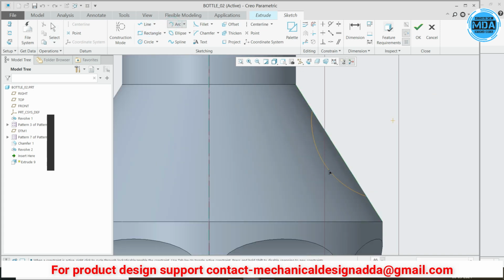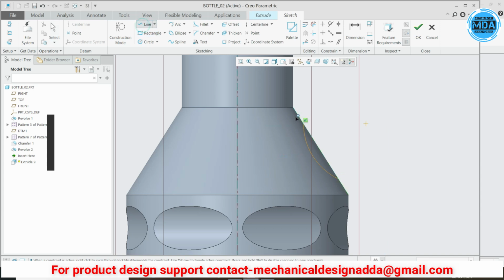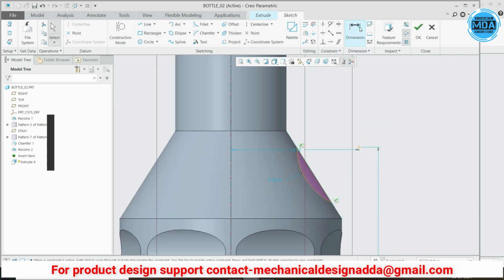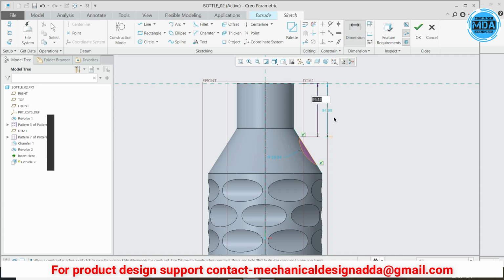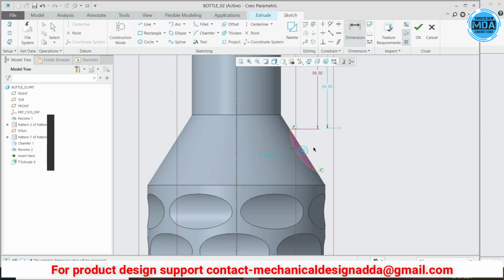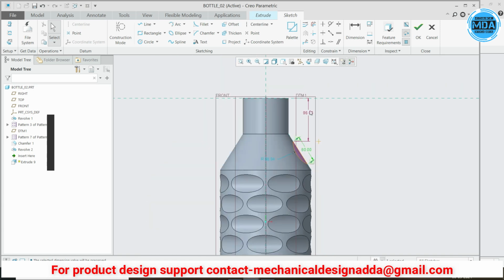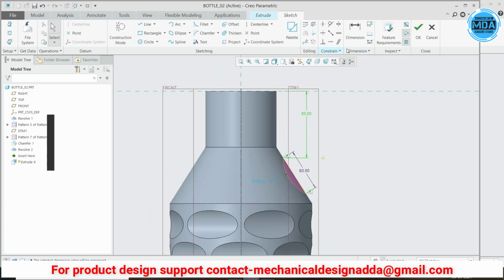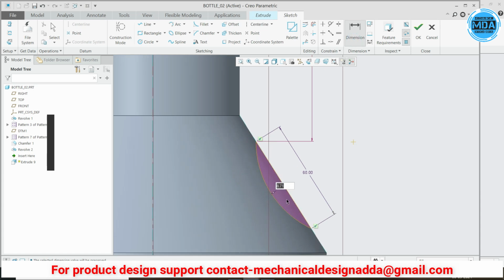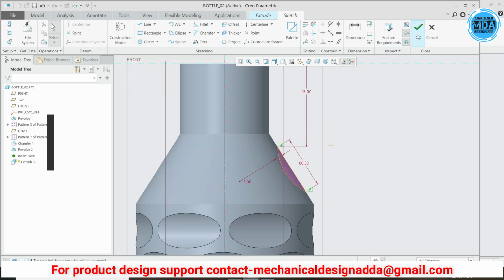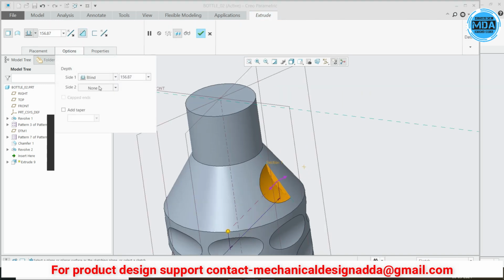I'll keep here the same geometry, and I'll dimension from the top, like 96 mm from the top. It will start the section, and the total length I'll keep here as 50, or you can say 60, okay, 60, and I'll keep this as 95. And the depth of the cut, I'll keep 8 mm. Yeah, so just remove this one with through wall, and here through wall, like that.